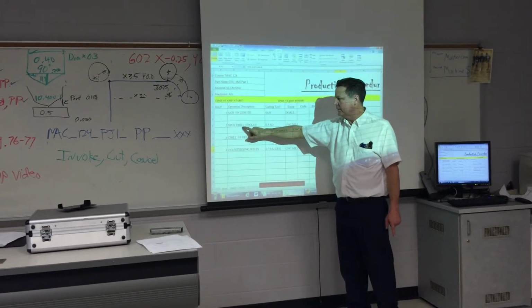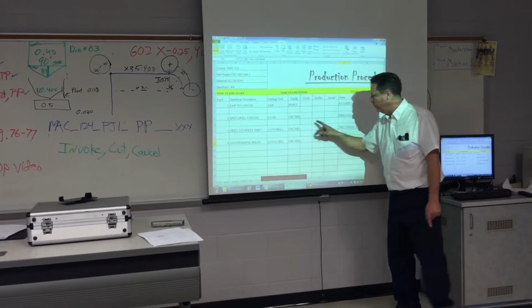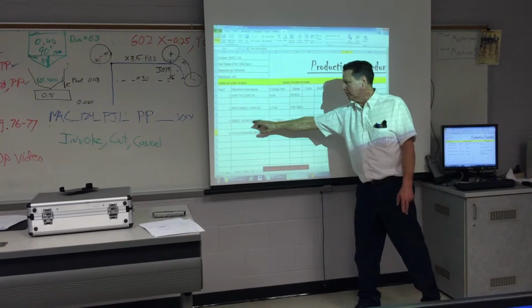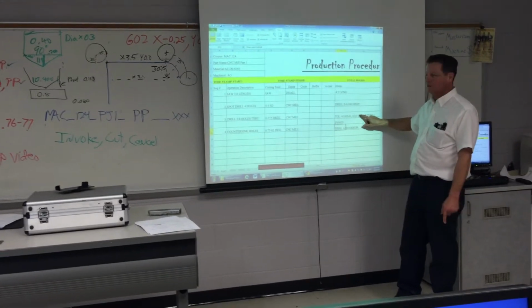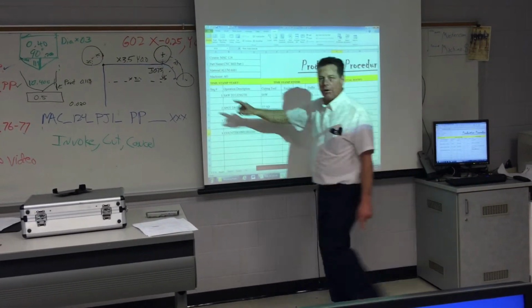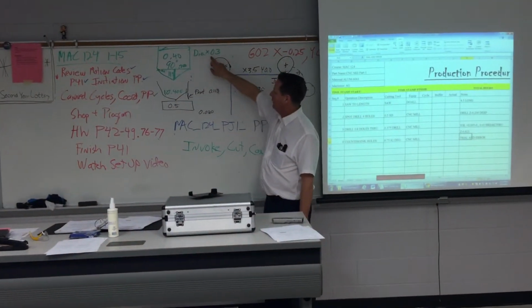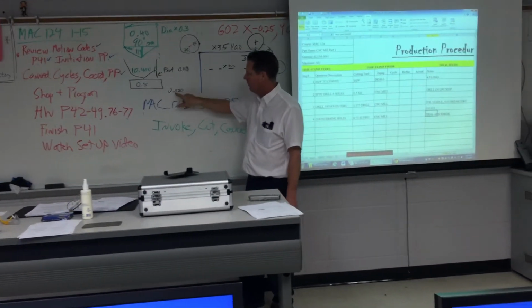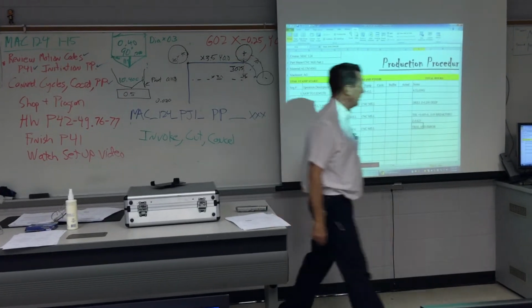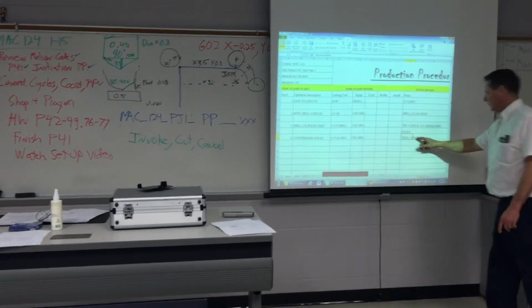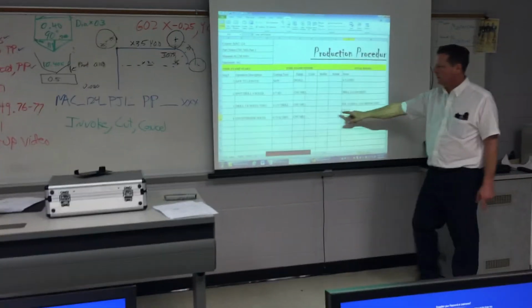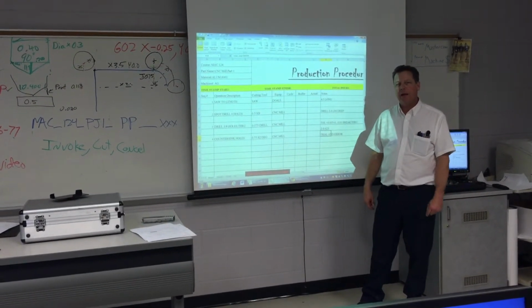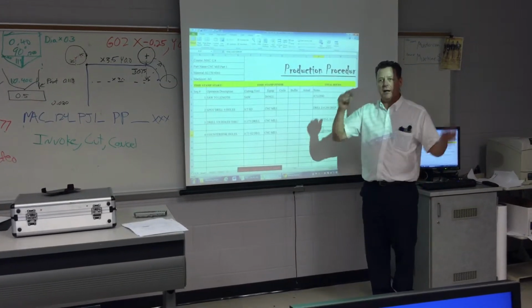The sequence 2 was spot drill the 4 holes. Over here in the notes, how deep we're going to spot drill those holes. Then we're going to drill the holes through with a certain amount of breakthrough. Later on, we use the formula for the drill point compensation. We figured the thickness of the part, and then 30 thousandths breakthrough. We had Z minus 0.623. Then we're going to countersink the holes with an 82-degree countersink and use trial and error to get it to the right depth.